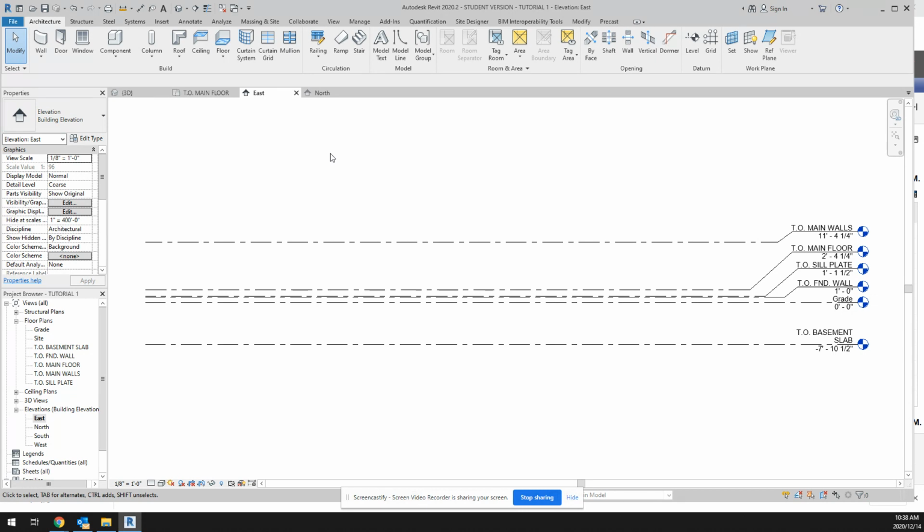Okay. So when we start drawing walls for our dream house, the first floor that you want to work with is your main floor. The main floor of your house plan creates the overall footprint for your building, which then will determine what your foundation looks like. And it also determines the second floor and any other floors above that, right? Because everything is below or above your main floor. So that first main floor is always the level that we start working with when we start drawing our walls for our house plan.